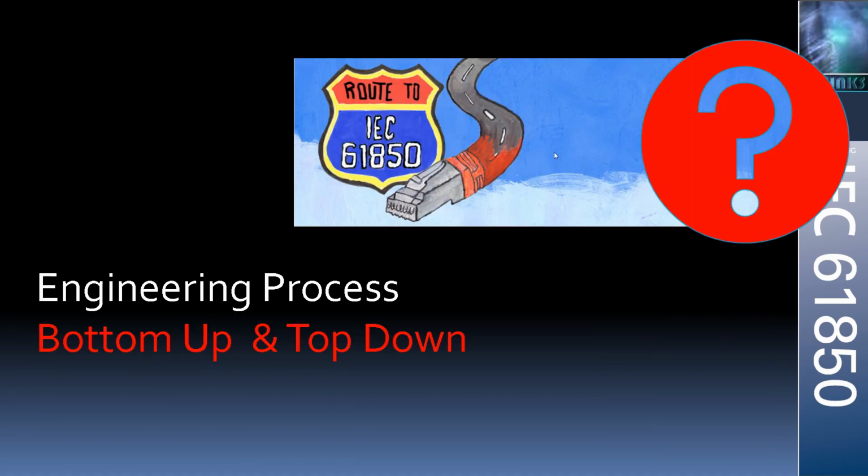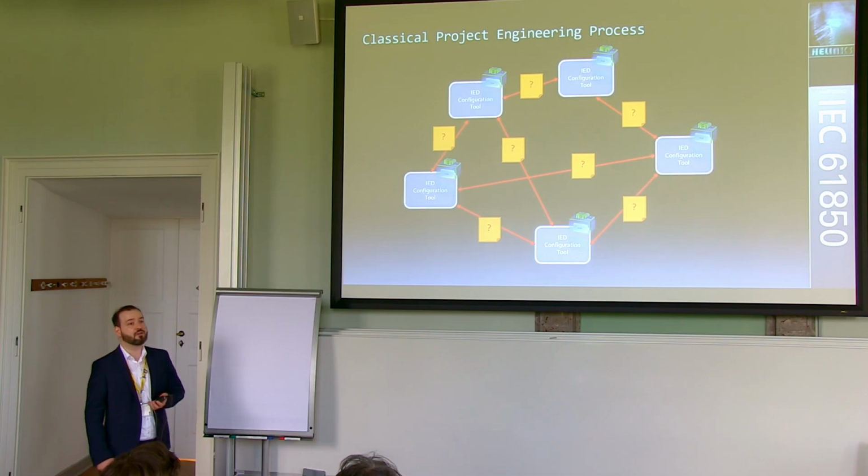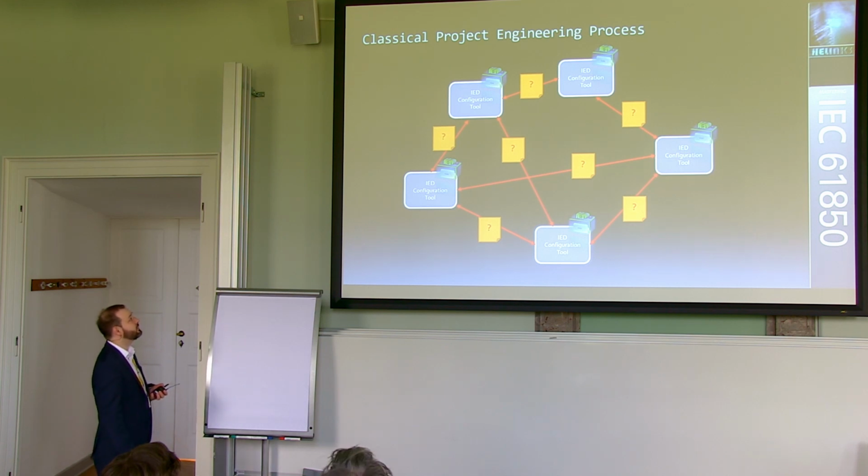But when we want to look at what happens in the SCL files, it's closely interwoven with the engineering process. When we come to a customer who starts with IEC 61850, this is something that we very frequently encounter. It's called the classical engineering process. Depending on how many different hardware manufacturers are in use, you will have a multiple of IED configuration tools.